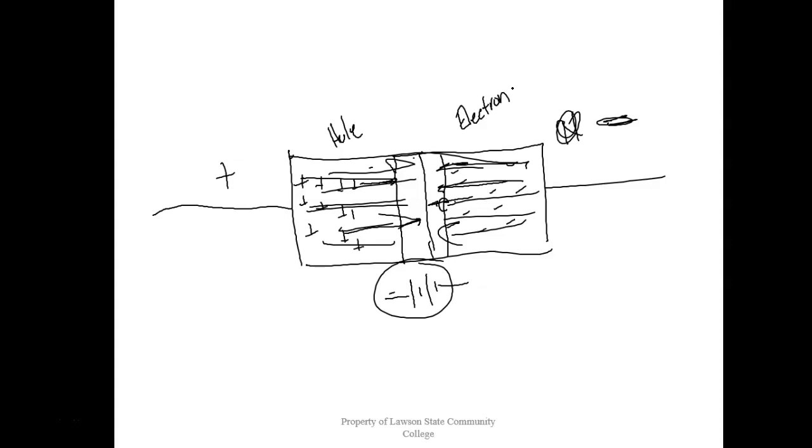These guys are pushing up against the depletion region. And eventually, if we get the voltage up high enough, it's going to break through, right? Does that make sense? And all of a sudden we have conduction. Now it's going to act a lot like a conductor. It's not going to be a semi; it actually acts like a conductor now. These combine in the center. This guy keeps pumping electrons in on this side, this guy keeps pumping in holes on that side, and all of a sudden it just avalanches as soon as we exceed this voltage right there, which we call the barrier voltage.